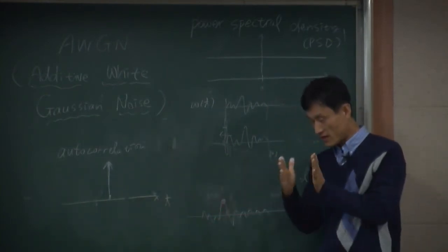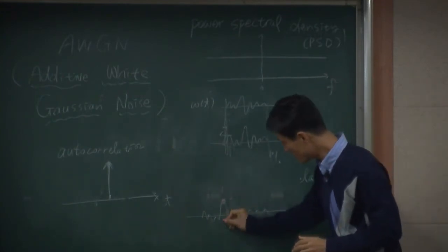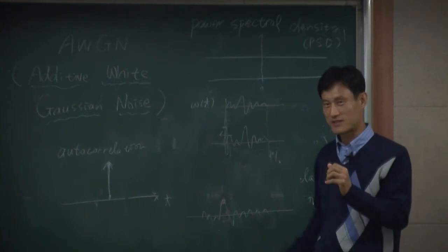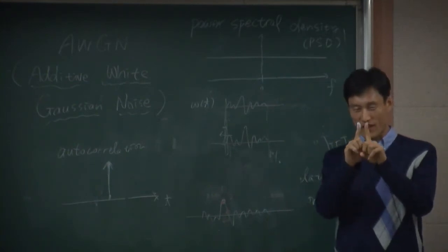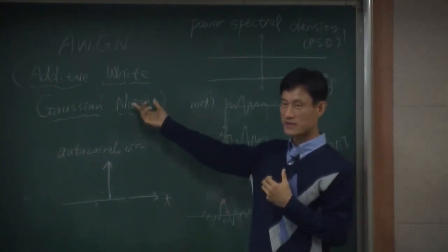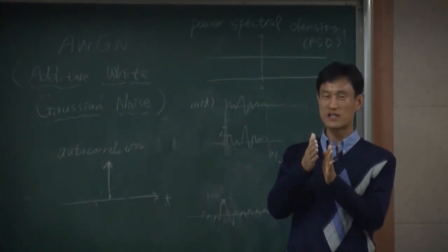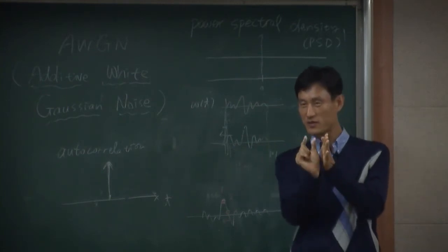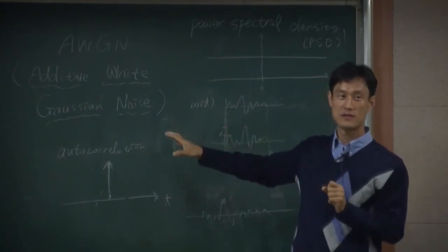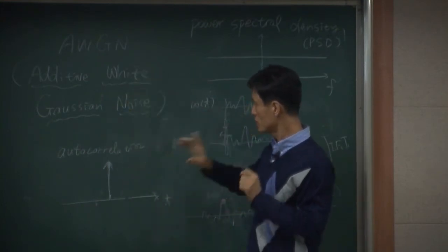Even though these two samples are very close, okay? Let's say in time domain the time difference between these two samples is 1 nanosecond, just as an example. These two noise samples are very, very close. What's the correlation? 0. That's our noise. So in our noise, simply speaking, there is no correlation between other samples. If you have a little bit of time mismatch, correlation is perfectly 0. That's our noise. Why? Because our noise is white noise. So you need to remember these things.